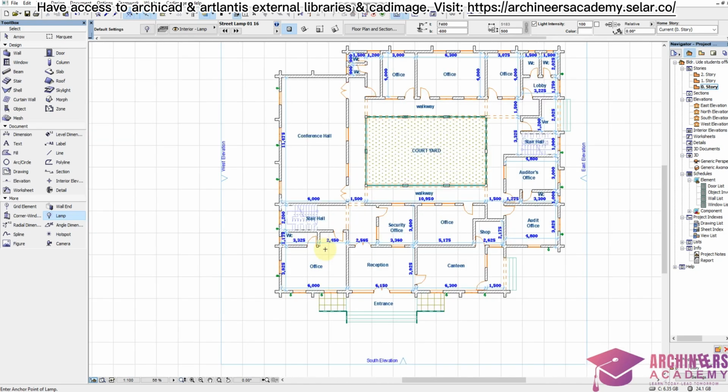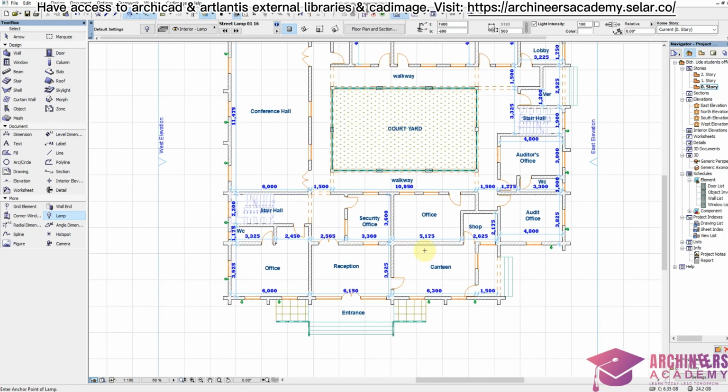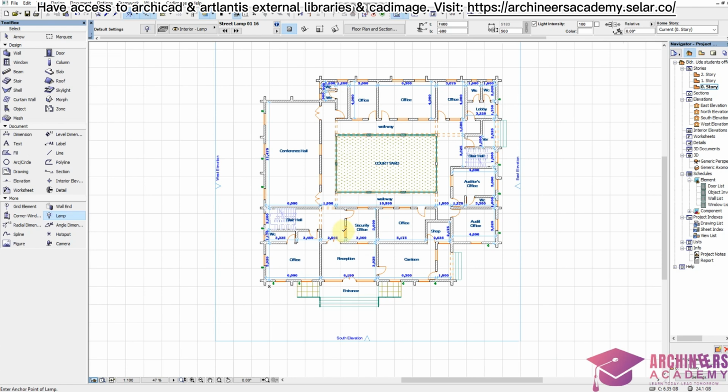So right now I want to show you how to put your grid lines, which is the first thing you will do in your working drawings. You must ensure that you have your grid lines. After you have done your interior dimensioning everywhere, ensure you put your interior dimension in and make sure that your dimension numbers are clear. Because if they're not clear, you are likely to produce that plan again, because your client or the builders need clear dimension numbers.